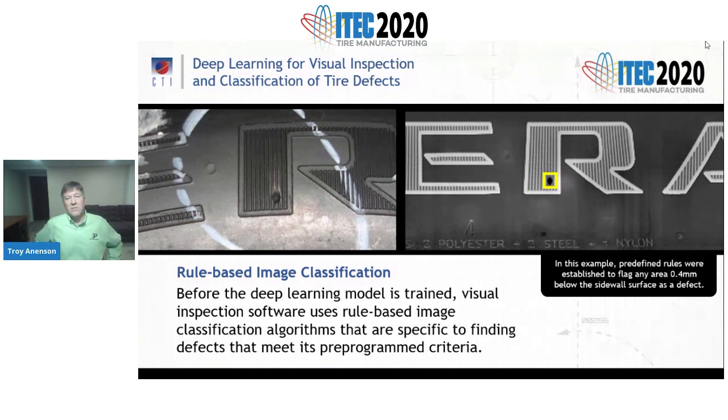Defects such as pits or blemishes from mold contamination, or gouges or similar damage from tire handling equipment, or unwanted pin vents or flashing, and damage from improper processing by upstream equipment such as grind appearance issues, can all be detected using smart rule-based algorithms employing statistics and thresholds to differentiate pass from fail. This is similar to the way the tire geometry systems look for bulges and depressions.